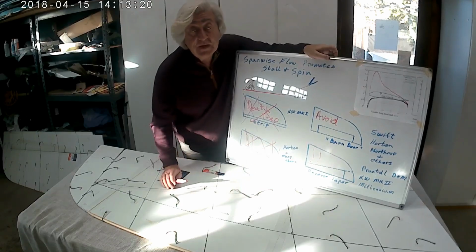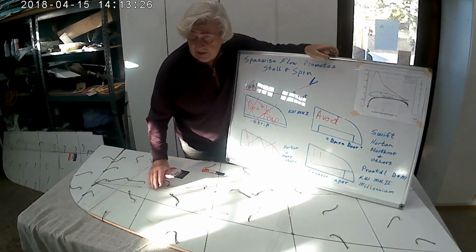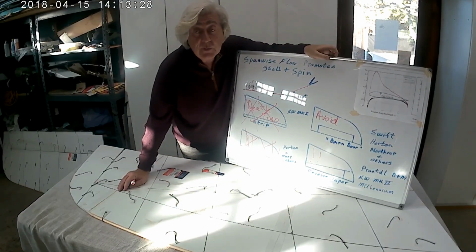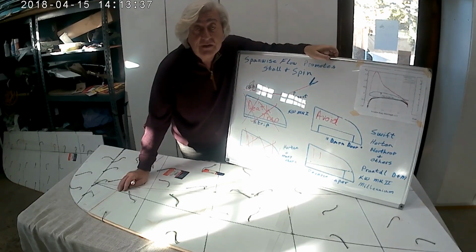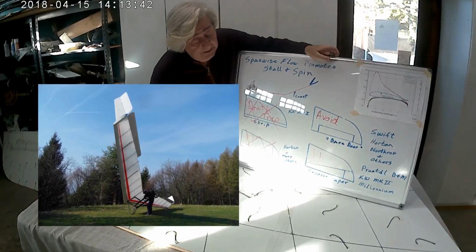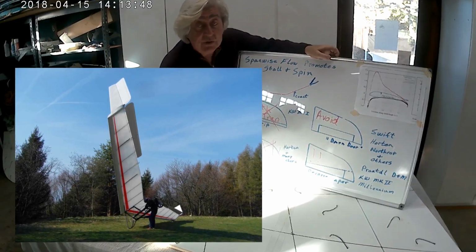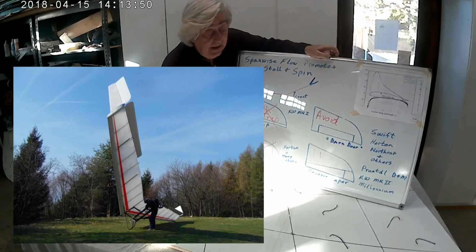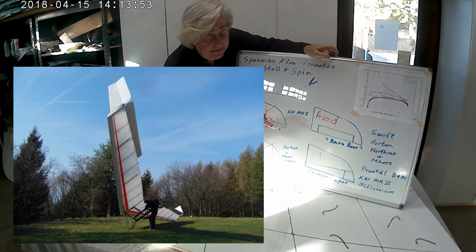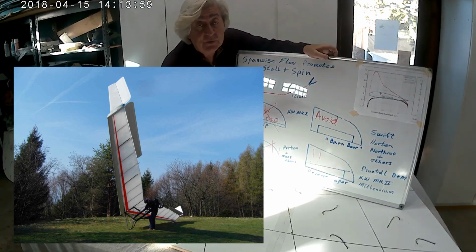In fact, from these flow tests that I just did, we see that this elevon extension out to my wingtips, to where my elevon is all the way up to the spar, is probably going to work out just fine, because we're in the flow field of maximum momentum, and I'll be able to do large controlled deflections without having issues with separating the flow or causing a lot of spanwise flow. And the Millennium, for different reasons, Steve Morse designed those elevons to reduce the induced drag, but as a consequence, you actually help prevent spins with that. Now, I hear the Millennium will spin, but you really have to force it into it.